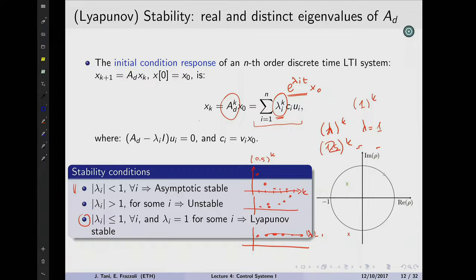Well, it turns out that as we say that the stability is regulated by the magnitude of this eigenvalue, but we haven't talked about the sign, right? It's stable even if it's minus 0.5. It's just that if you have the minus, then every time instant you're switching sign, because an even power of a negative number is a positive number and so on. So if you had lambda equal to minus 1/2, for example, which would still give you asymptotic stability, it would bounce up and down like this, okay? So you would get the equivalent of your oscillations before.